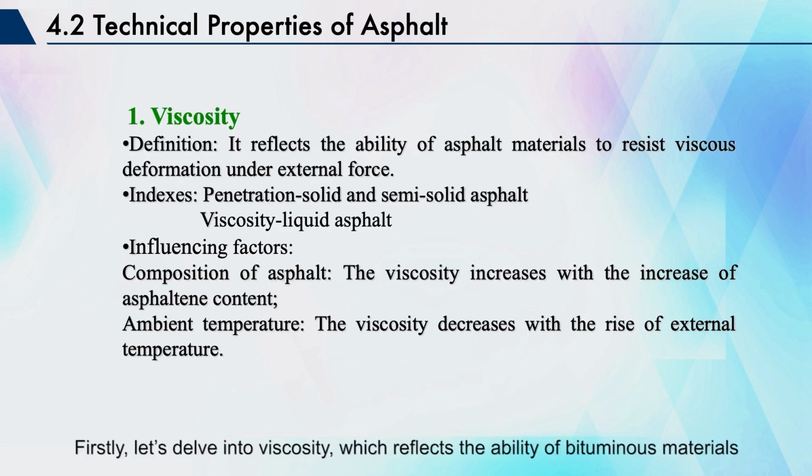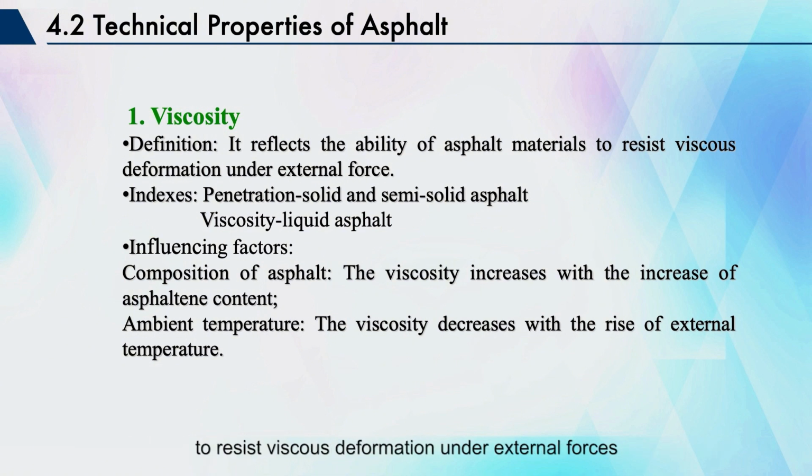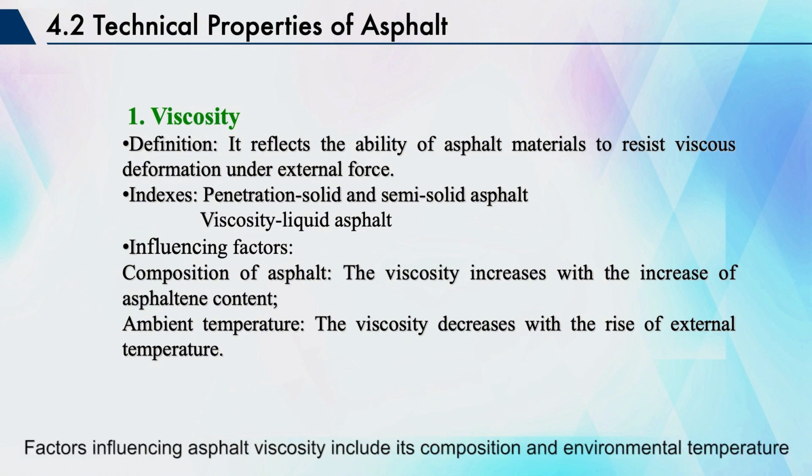Firstly, let's dive into viscosity, which reflects the ability of bituminous materials to resist viscous deformation and external forces. The technical indicators that reflect asphalt viscosity primarily include penetration and viscosity. Penetration measures the viscosity of solid and semi-solid asphalt, while viscosity characterizes the viscosity of liquid asphalt. Factors influencing asphalt viscosity include its composition and environmental temperature.